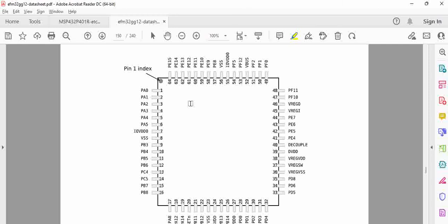which is basically called multiplexing. So in a microcontroller, with just a 64 pin package, you cannot have all the features on all the pins, right? So there is something called multiplexing that happens in a microcontroller, where each and every pin will have multiple functions. So you need to understand which pin has that multiplexing function, and you need to configure in the firmware such that the pin acts as per your requirement.